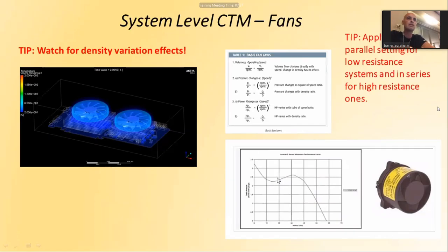This area is not stable, so you won't work here. If you have a simulation or if you do an experiment, you'll actually see it ticking from one to another. It destroys the fan, and this fan screams. So there's a lot you need to know about fans before you decide which fan you use.